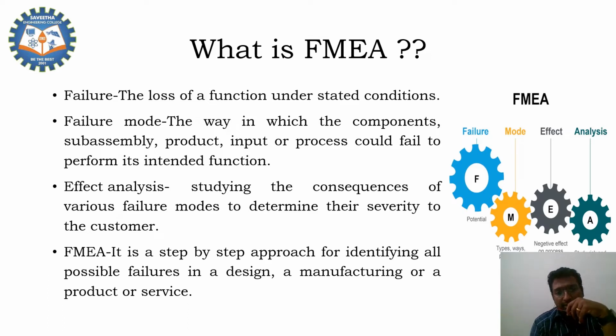What is effect analysis? Effect analysis is studying the consequences of various failure modes to determine the severity to the customer. There are many failure modes. Based on the failure mode, we can identify how severe the failure is, whether the failure can be tolerated or cannot be tolerated. That is the severity level. So what is FMEA? It is a step-by-step approach for identifying all possible failures in a design, a manufacturing process, or a product or service.